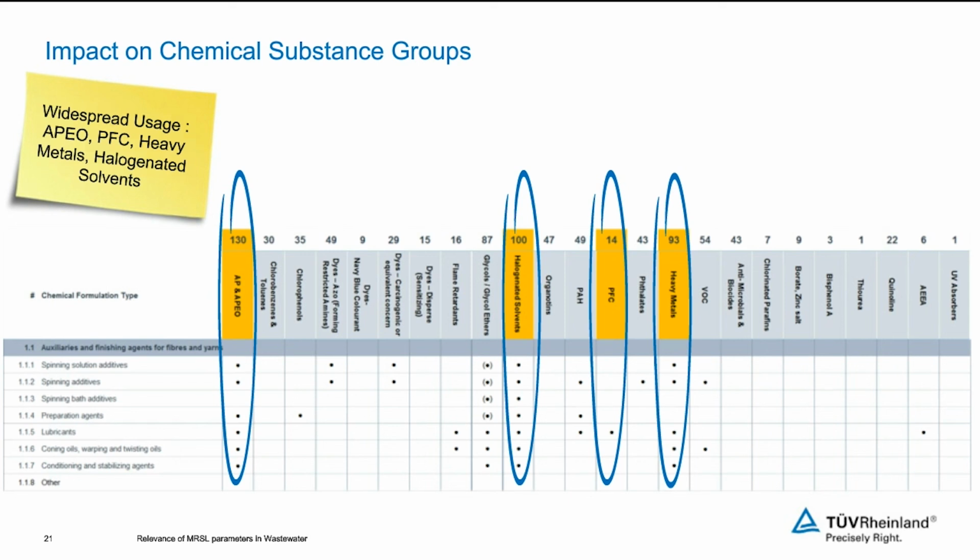And manganese may also come from wastewater treatment chemicals like polymeric ferric sulfate, because polymeric ferric sulfate is produced from ores. Manganese is also present in the ores, so manganese will exist as a contaminant in the polymeric ferric sulfate, and if factories treat the wastewater with it, the manganese will also go along with these chemicals into the wastewater. Yeah, thank you. Thanks, Arrow.